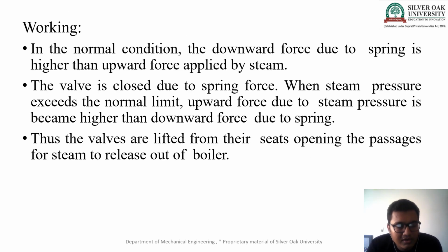Now, the working of the spring loaded safety valve. In the normal condition, the downward force due to the spring is higher than the upward force applied by the steam, so the valve remains closed due to the spring force. When the steam pressure exceeds the normal limit, the upward force is more compared to the downward force. Because the steam pressure becomes higher than the downward force due to the spring, the valves are lifted from their seats, opening the passage, and the steam is released from the boiler to the atmosphere.